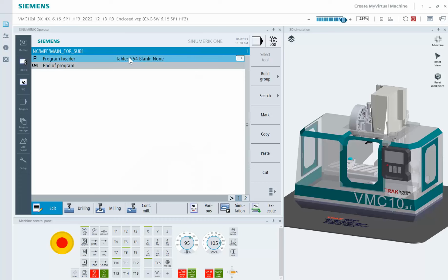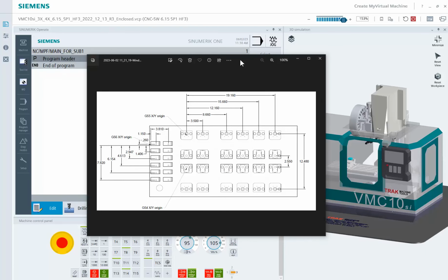So really the first step is, where is my 0 on my fixture? And then how do I shift that 0 to some new location? If I look at my part, for simplicity's sake, I'm going to say that the middle of my fixture is my Y0. I'll use his dimensions to give us something to work from. Just because of where all these dimension lines are coming from, I'm going to have that middle point be my 0.